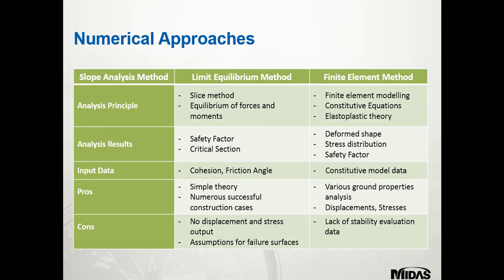So now we're going to focus on the numerical approaches for slope stability analysis. Two analysis approaches are considered: the limit equilibrium method and the finite element method. So first of all, we'll just focus on the LEM and the analysis principles. It divides the slope into vertical slices and calculates the safety factor by considering the equilibrium of forces and moments.